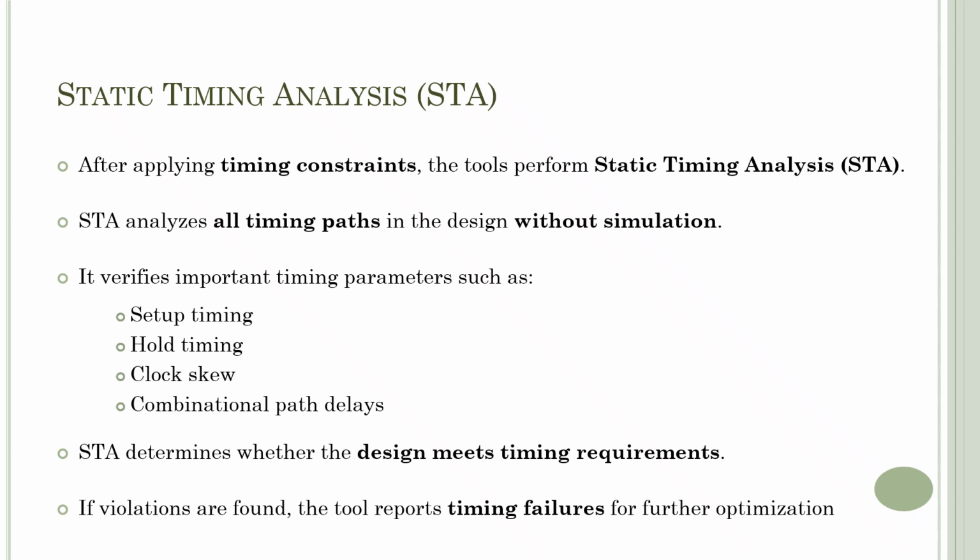During this analysis, STA verifies several important timing parameters. First, it checks setup timing. This ensures that the data arrives at the destination flip-flop before the required clock edge so that it can be captured correctly. Second, it checks hold timing. This ensures that data remains stable for a short time after the clock edge, preventing incorrect data capture.